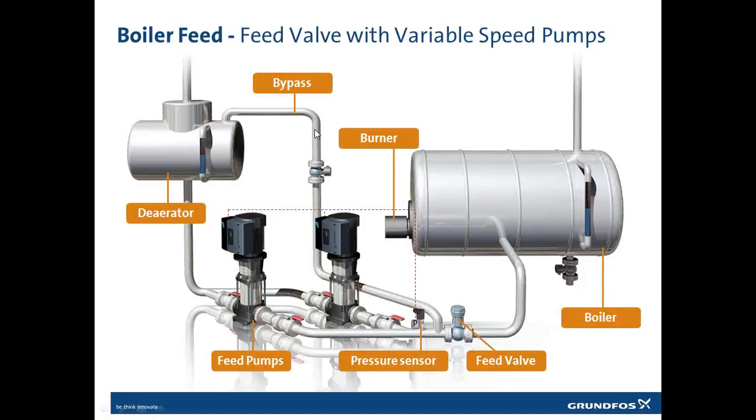Actually, the NPSH curves are drawn on 20 degree C de-aerated water. That means that the NPSH curves you find on WebCAPS, on Product Center, and in the data sheets are not correct when we are talking boiler feed and we are operating with 221 degrees F, or 105 degrees C, water.